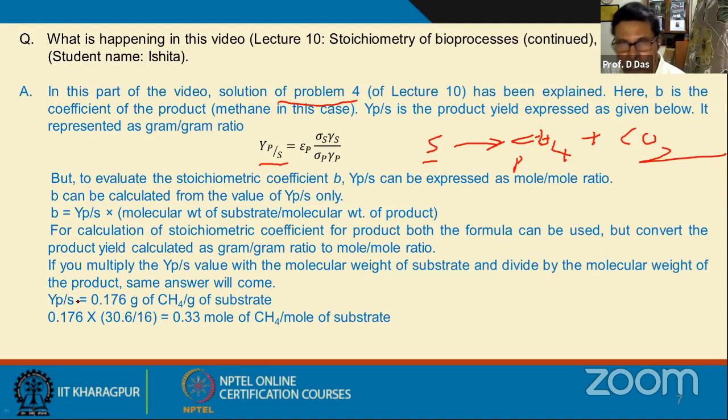Suppose you take a solid material and dry it, and then you burn it in presence of oxygen. How do you burn it? You keep it in the oven at 600 degrees centigrade for a couple of minutes. All organic matter will be burned, and whatever material remains, we consider to be the oxides of the metals, and that is considered as the non-volatile component. The volatile components of any kind of solid material we usually consider as the organic material, and the non-volatile components we consider as a metallic residue present in the particular solid residue.